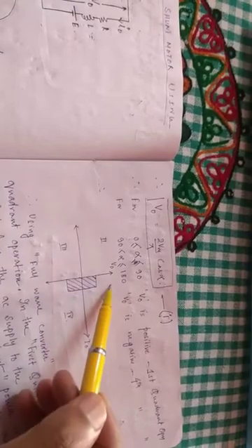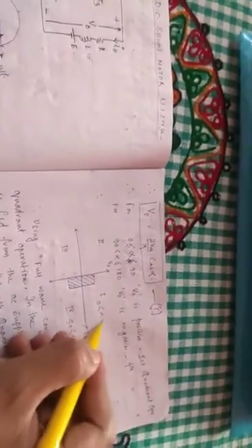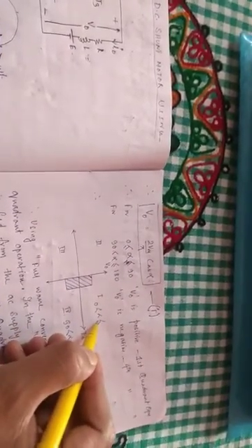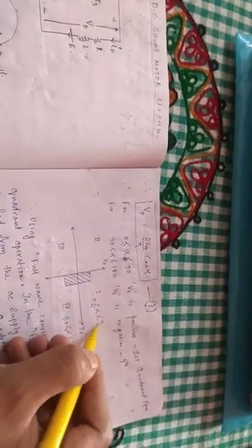What can change direction is this V0 with the variation of alpha. So with the variation of alpha, this two quadrant operation is possible, one in the positive V0, negative V0, and this negative V0 is for 90 less than alpha less than or equal to 180 degree, and this positive V0 is for 0 less than or equal to alpha less than 90 degree. So now using full wave converter we get two quadrant operation.